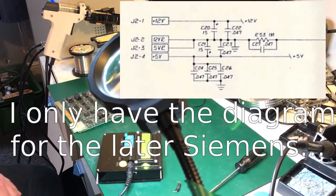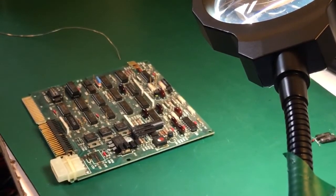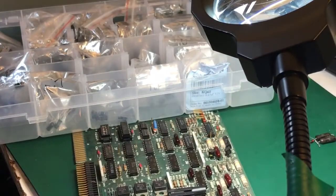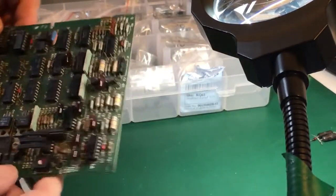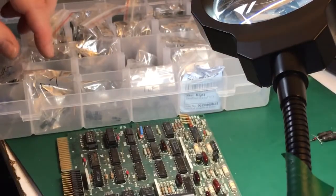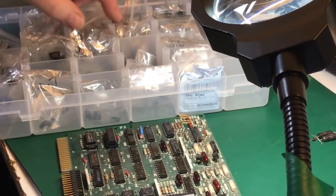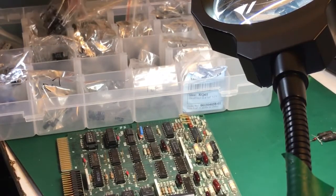We're going to check the circuit diagram and decide what we're going to do about replacing them with electrolytic. I'm fairly certain they're just 22 microfarad capacitors, which we should have something we can use in the capacitor box. That's a 20-something volts, so as long as we've got it well above the 12 volt headroom, we'll be fine. 15 volts. Okay, so we should be able to find something. And the 22. That's that 220. I think we must index these a bit better.